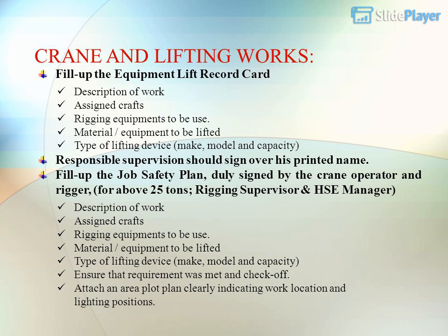Fill up the job safety plan, duly signed by the crane operator and rigger, and for above 25 tons, the rigging supervisor and HSE manager. Description of work. Assigned crafts. Rigging equipment to be used. Material, equipment to be lifted. Type of lifting device, make, model and capacity. Ensure that requirements were met and check off. Attach an area plot plan clearly indicating work location and lighting positions.